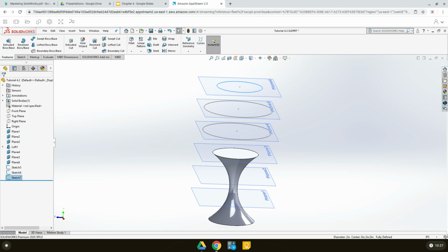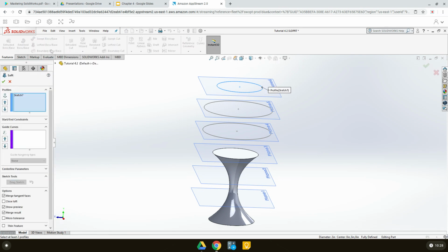So once again we need to use the lofted feature, but this time it will be different because we need this to be a hollow loft, not like this solid loft. So let's use the Lofted boss command, and let's select each of the circles on the same side. So one. Okay, this is what happens. I accidentally had this circle selected, and then I selected this, so it's twisting. So I need to clean everything here first, and then start from scratch.